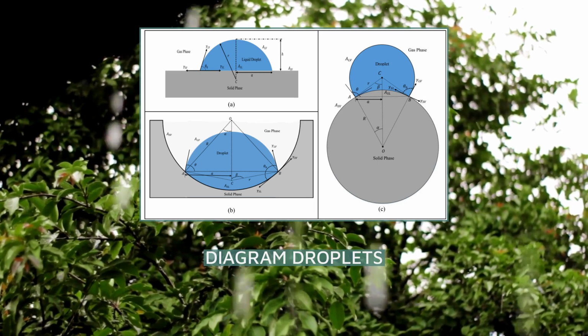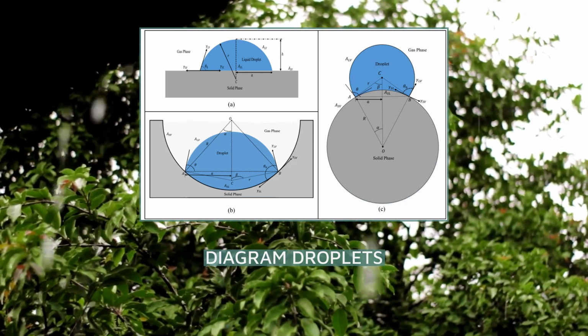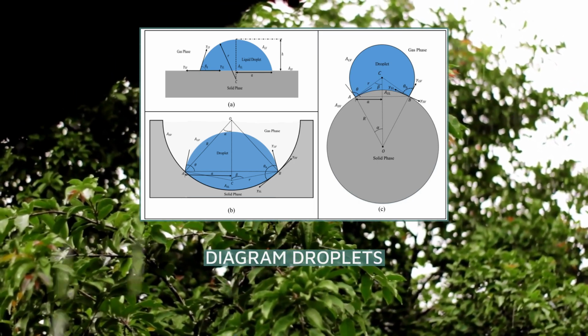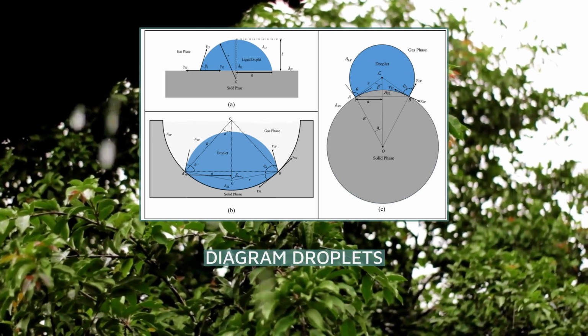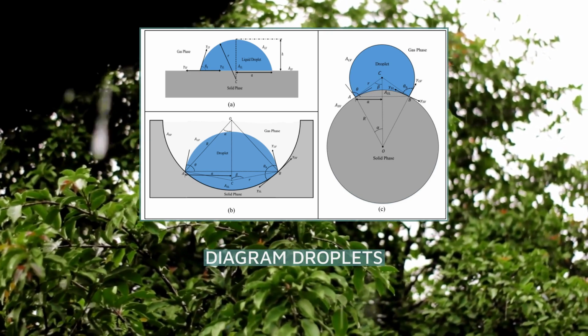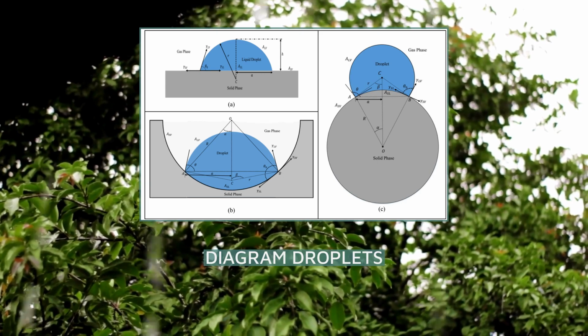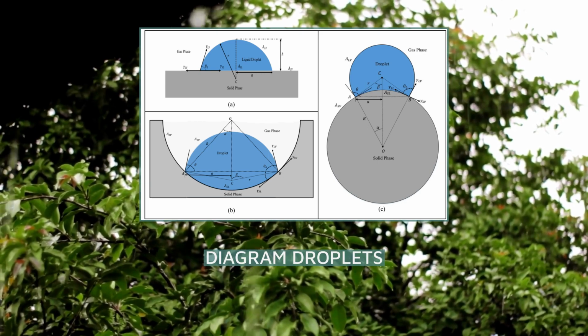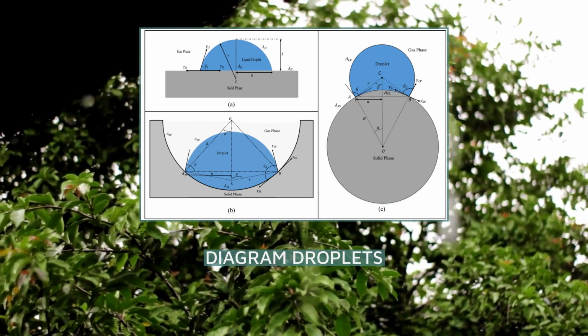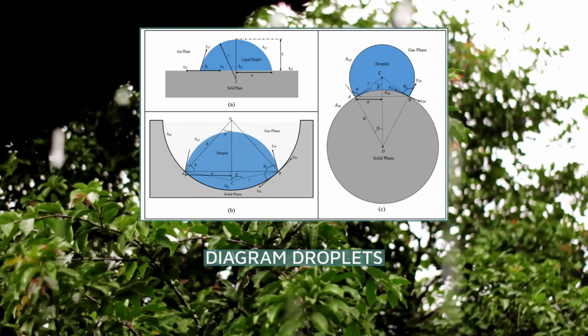Usually, the VdP term has been neglected for large droplets, however, VdP work becomes significant at small scales. The variation in pressure at constant volume at the free liquid-vapor boundary is due to the Laplace pressure, which is proportional to the mean curvature of the droplet and is non-zero.